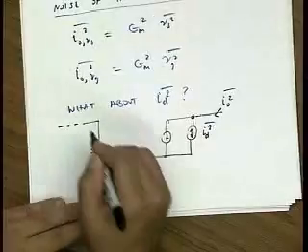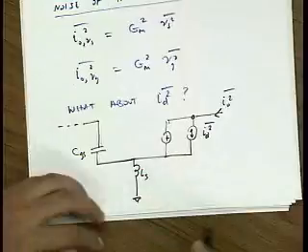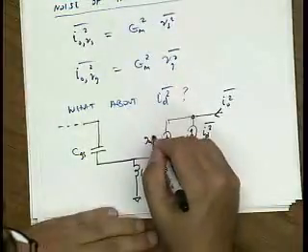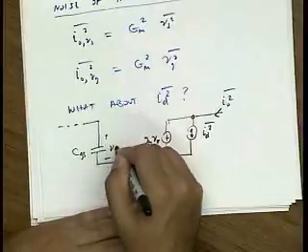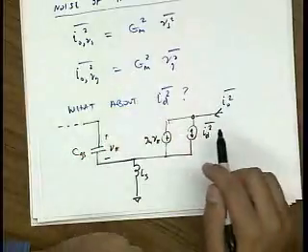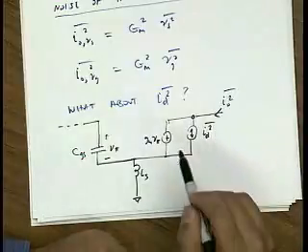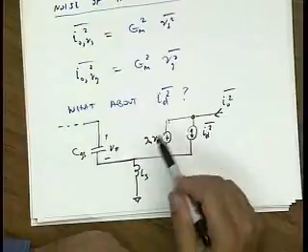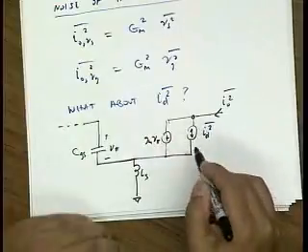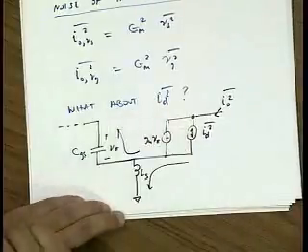So this is CGS, this is LS. Now it seems like this noise source just flows straight into the output, just like a common source device. But you can't neglect the contribution of this transconductance, because this current source will partly flow into here and partly flow into here, right?